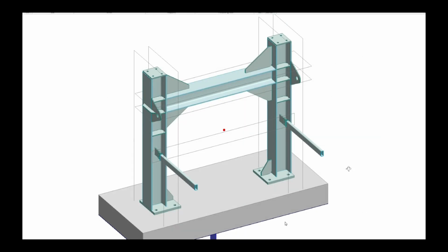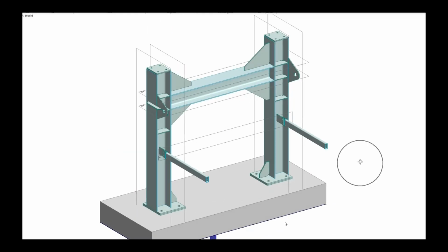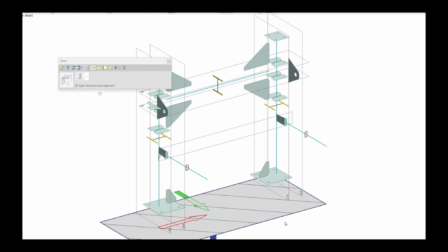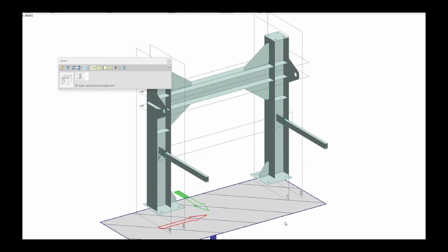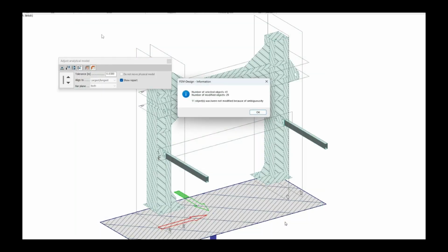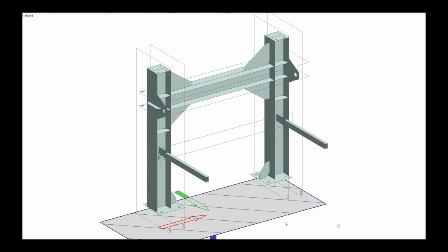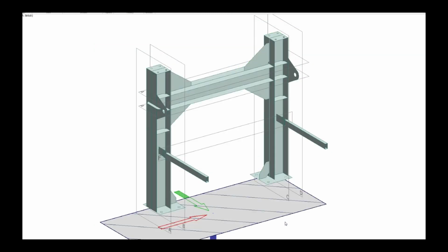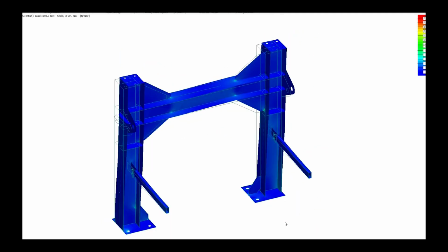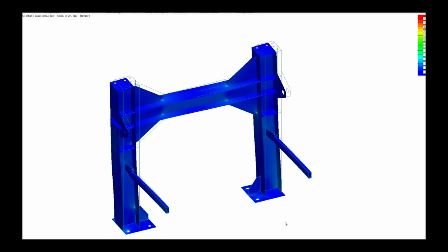In the second example, we import this model to the finite element software. So we use IFC beams and IFC plates to import this structure. Then we can convert those beams to shell models, and then we can connect those shells together and stretch them to our master objects, and then we are done, and we can already run analysis because we can achieve a really high quality mesh. So anything can be imported. This is steel, but the same applies to anything made out of concrete.